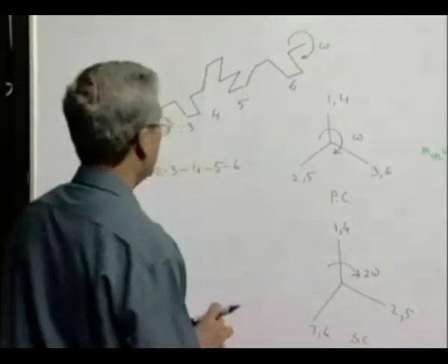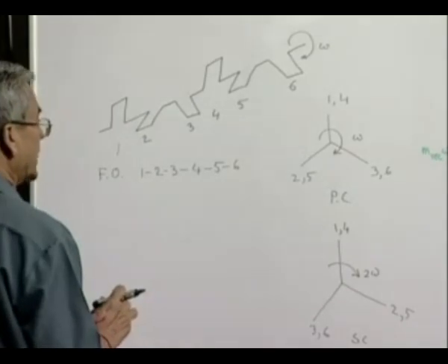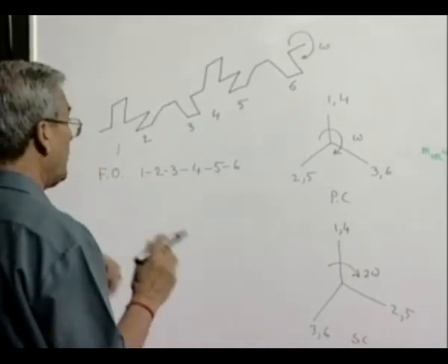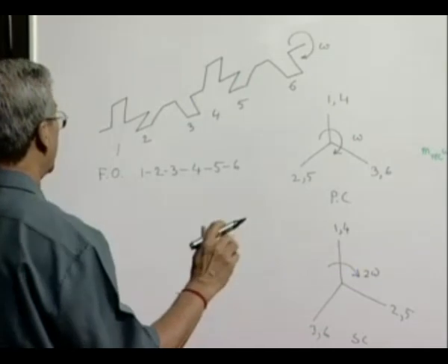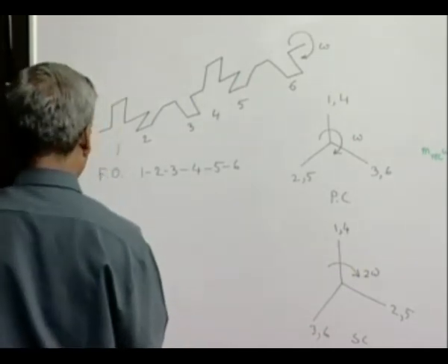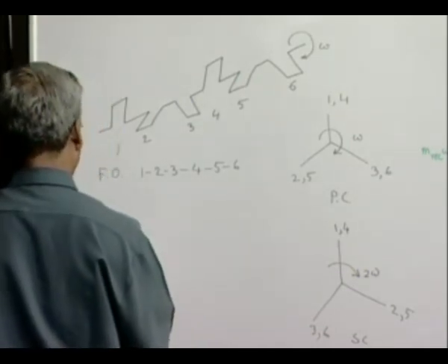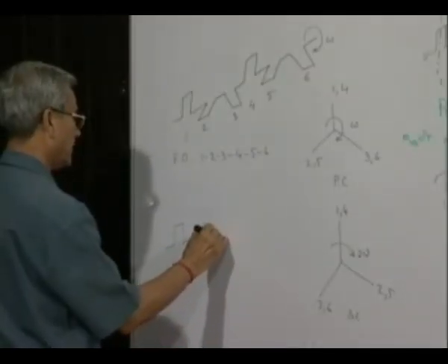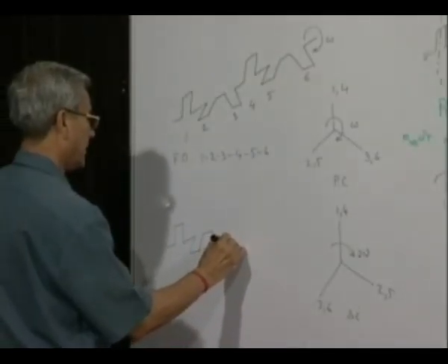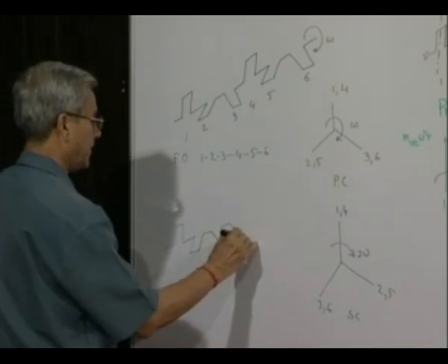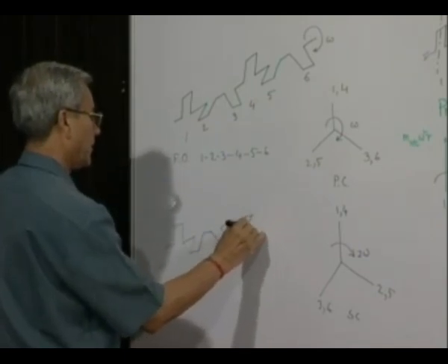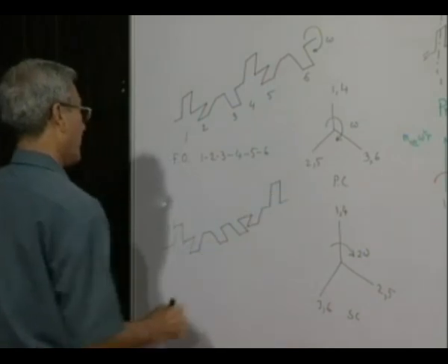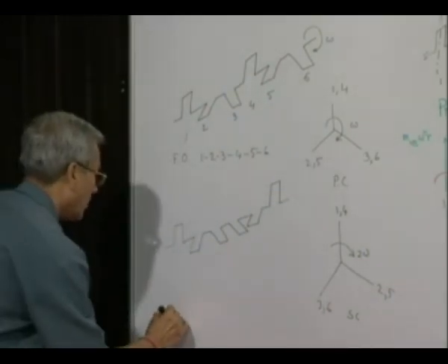To achieve both primary and secondary force balance, to achieve primary and secondary moment balance, complete balance up to secondary, we have to take crankshafts which are symmetrical like this. Either this or this.